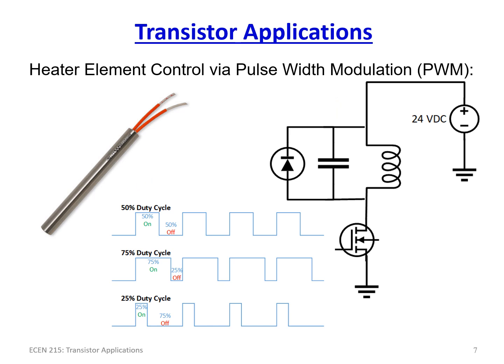So at 50%, heaters don't respond quickly mechanically. The actual thermal energy does not respond at 1 kilohertz. Just the heat energy does not. So what ends up happening is it averages out over time. So the average ends up being I equal to 24 volts divided by, let's just say, 1 ohm, times our duty cycle. So you end up equal to 12 amps. So you've reduced your energy by that factor.